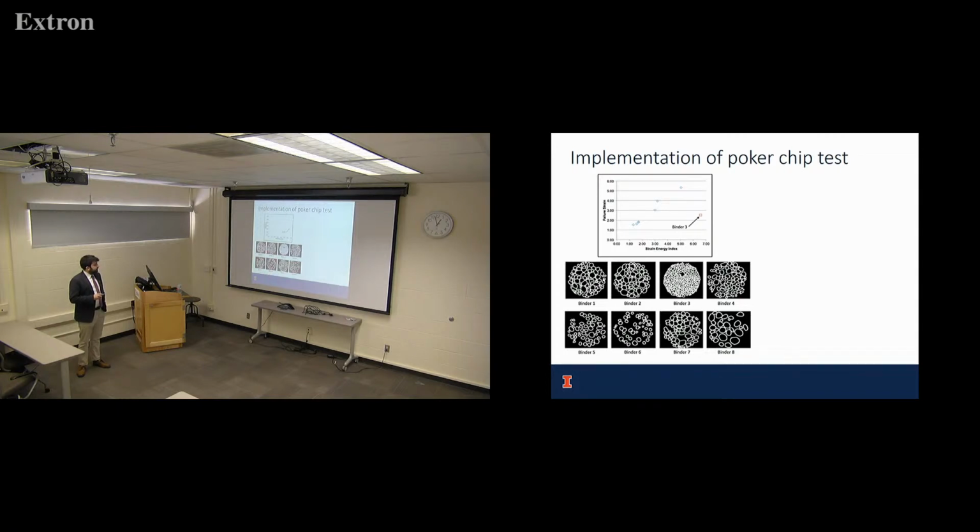And what we notice immediately, this is actually a binarized image of the cavitation surface. This binder 3 is a really strange one. It had very small cavities and a very high number of cavities. So we said, why is that? What's going on there? When we took measurements, it also had an incredibly low strength compared to other binders. That's basically what this graph means. You can see a very linear relationship for the others, and then just one random point here, that's binder 3. That's because of a very low strength compared to other binders. It was about half as much as other PG64s, roughly.